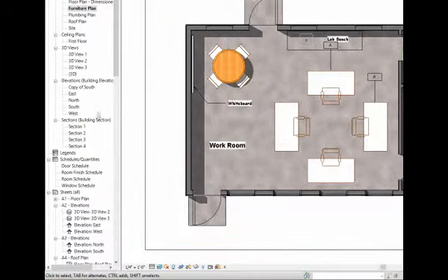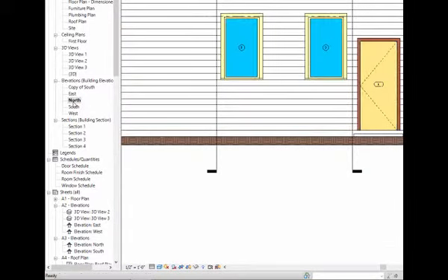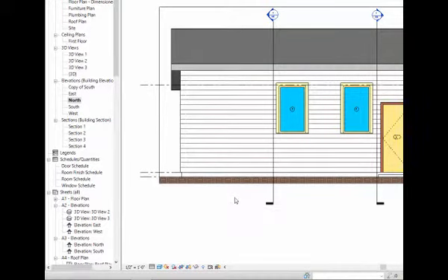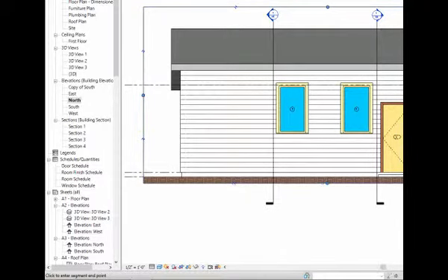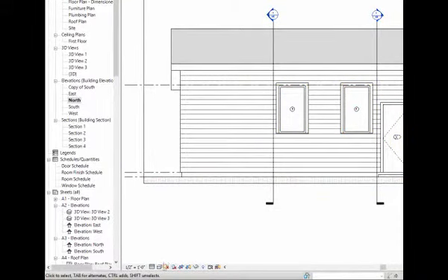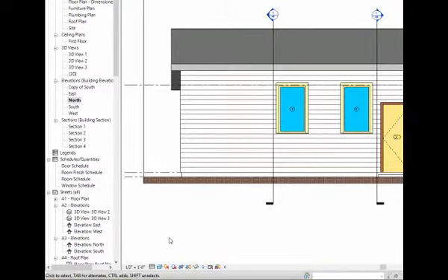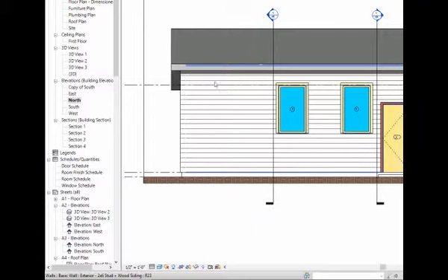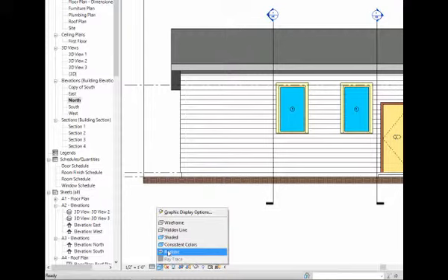Okay. Same thing actually works for your elevation views. Let me show you those. So on the elevation views, let's go to that north elevation, for example. Zoom to fit this. Okay, Hong's already done a pretty good job of just cropping it. That looks pretty good. He looks like he has a shaded view right now. Again, we can make it hidden line to take out the color, or shade it. If I'd like to show the shadows, that's again one of the tools at the bottom. Shadows are off right now. Let's turn them on. Now, the shadows aren't very dramatic here because he doesn't have much of an overhang. You could also make that realistic.